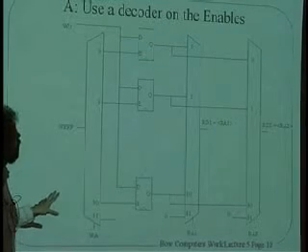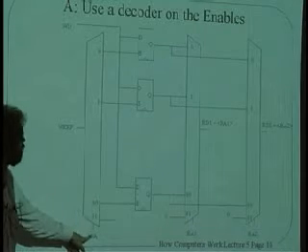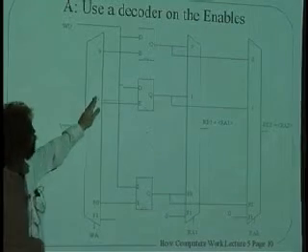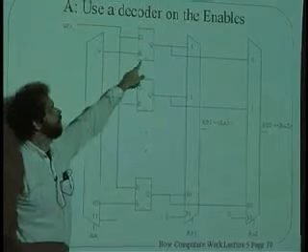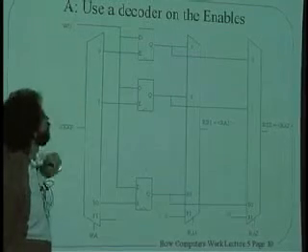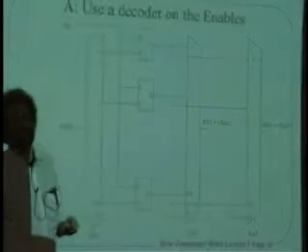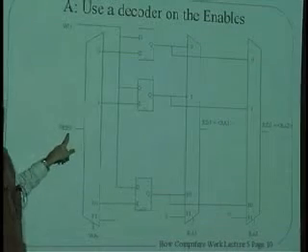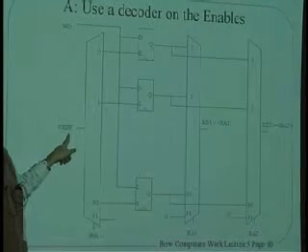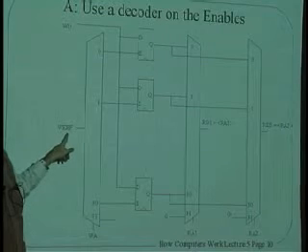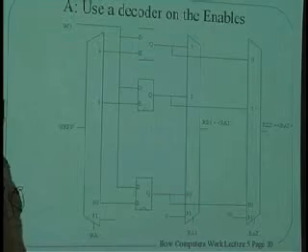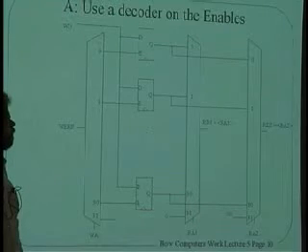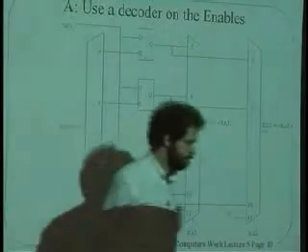And what that really means is, let's say we're writing to register number 0, and this wire is connected up to the 0 up here. It's saying, should register 0 pay attention to the data that comes in here when the clock goes off? And if WRF is 1, then the answer is yes. And if WRF is 0, then the answer is no. So it will not write always something. It's just 1 bit, either 0 or 1. Okay, so that's the general idea.